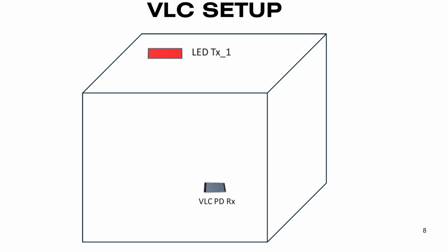If I briefly tell you about responsivity of the receiver, it basically defines how much electrical current is induced per unit of the incident optical power, and we measure responsivity in amperes per watt. So, in simple terms, higher responsivity means higher conversion ratio.